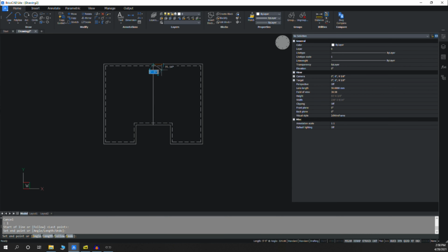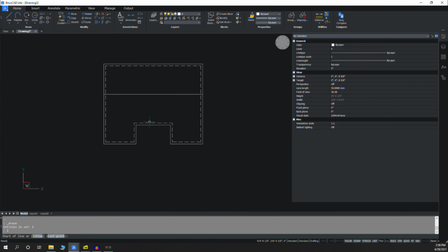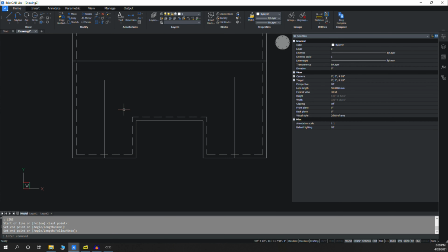I've got to get the center line of this because I lost it when I put these gables in, and now I've got the center of the main roof here. Just draw a horizontal line. Again, I'm having trouble picking up that point, so I'm just going to overdraw and then trim away the excess. I don't need this point anymore. And then let's pick up the center lines of our gables. We're not really sure where they're going to end up on the roof, but I'm just going to go a little bit further back there.